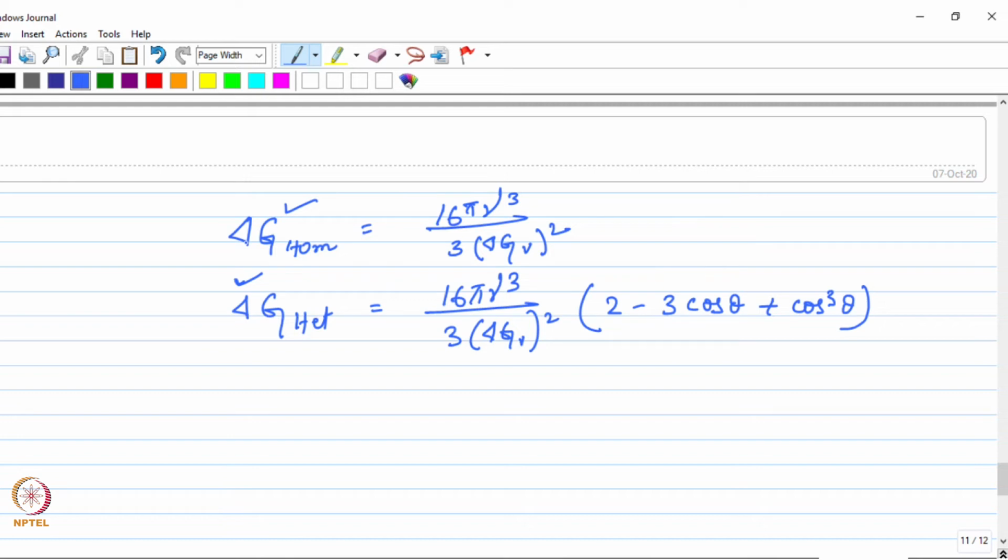So that is how you get a higher nucleation rate in heterogeneous nucleation, and the higher the nucleation rate, the lower will be the grain size. That is how heterogeneous nucleation leads to a finer grain size in the solidified material.